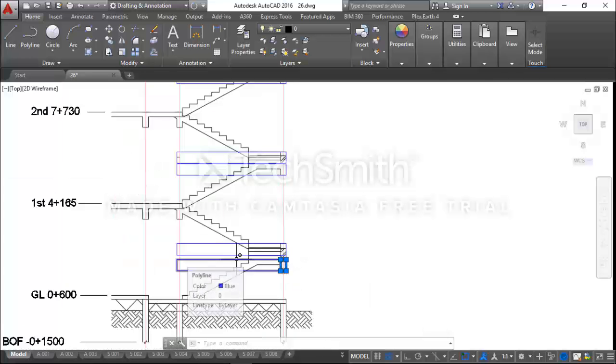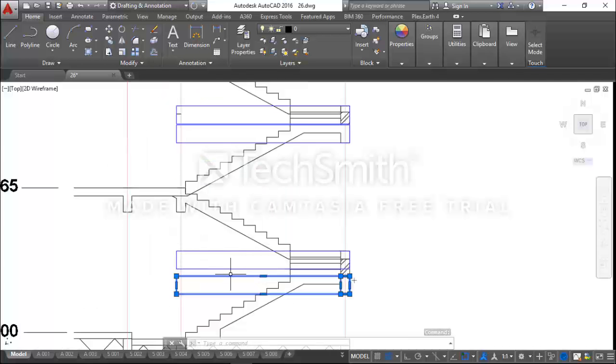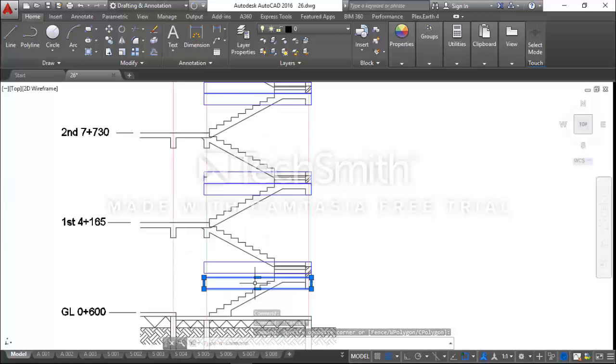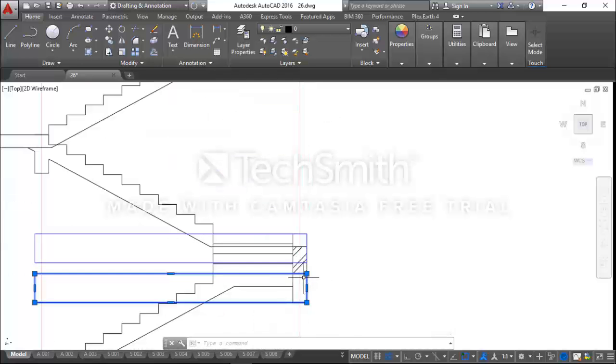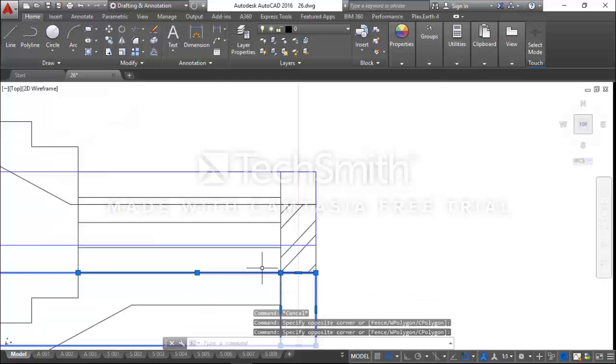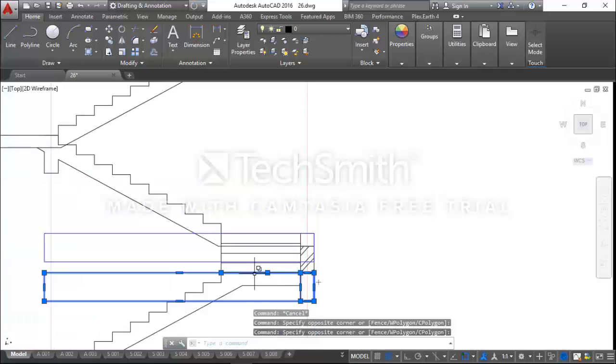In the other direction, this blue line represents the beam at the line 2. This drawing now will make sense to you. The blue line represents the beam at the line 2, and as you can see, it's at the same elevation with this beam. You can see they are together. So the elevation 2 is 2170.